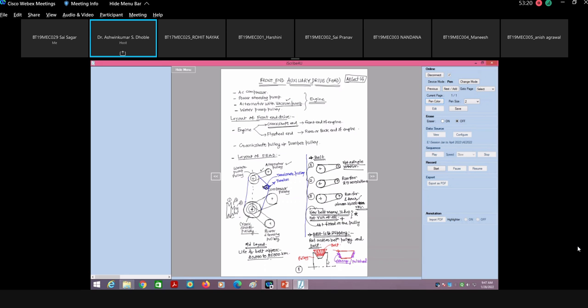polished means worn out, shining means the gloss that comes on metal after it is rubbed. So if you see the same kind of surface, then for sure you have to adjust the belt tension, as there is some problem with the slipping of the belt. So that is one thing. And there is another way to identify whether there is belt slippage in the vehicle or not.